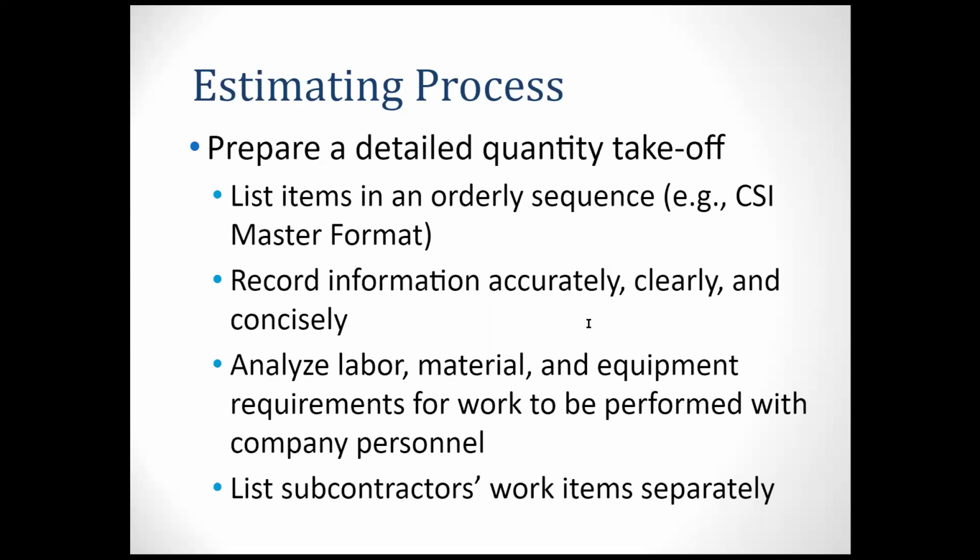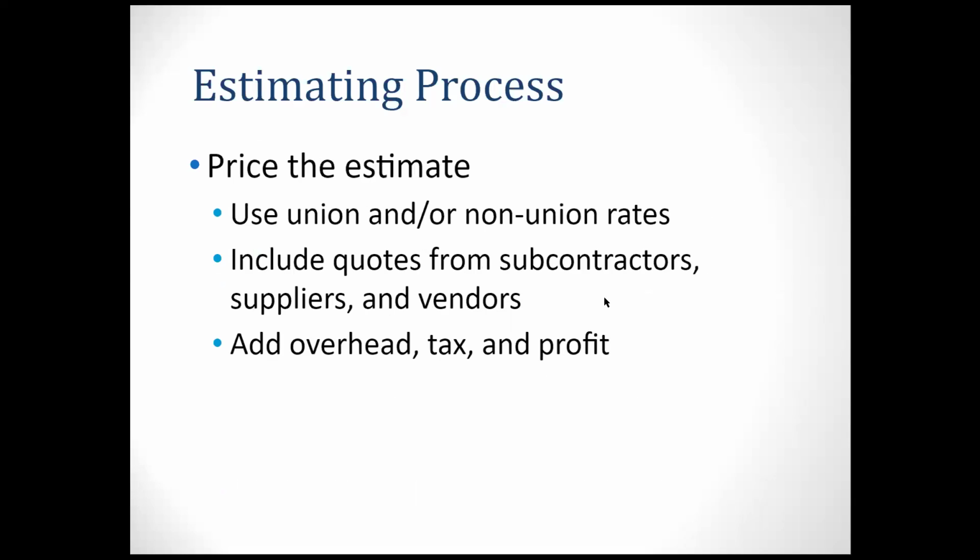And the next is the price, the estimates. Once you finish your takeoff, then you go into the price. Price is basically based on your company history data, right? If you don't have company history data, you may refer to data like RSMeans data, right? That is the national average or regional average. If you are working in a union area, which is not here, here is non-union, but in the Midwest they have unions, so the labor cost is different, right?